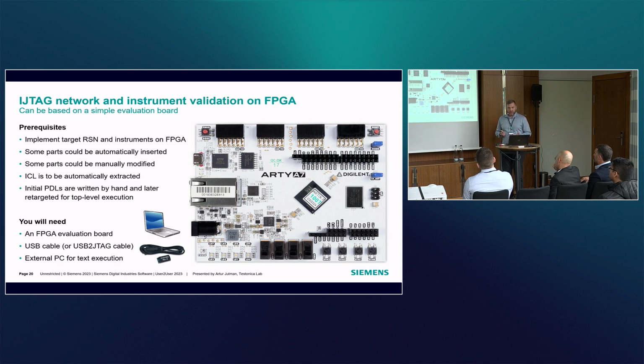Since there is manual interaction, that's another reason why you would like to simulate and validate your design, both in the simulation tools and maybe also on FPGA. But ICL could be automatically extracted, and the initial PDLs would be written by hand for instruments, and then they would be retargeted for top-level executions through JTAG.